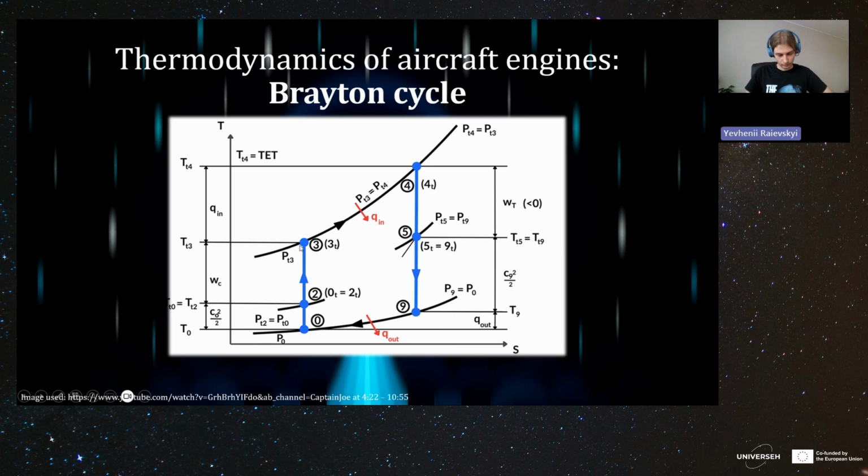And after the compressor stage, the next stage, as we remember, is the combustion chamber, represented in this arrow going up. And in this arrow, of course, temperature is increasing very fast. And so is the entropy, because here the reaction occurs, and the reaction occurs with more chaos, which is how we can understand entropy as a physical thermodynamical quantity. This entropy increases, and the temperature as well.